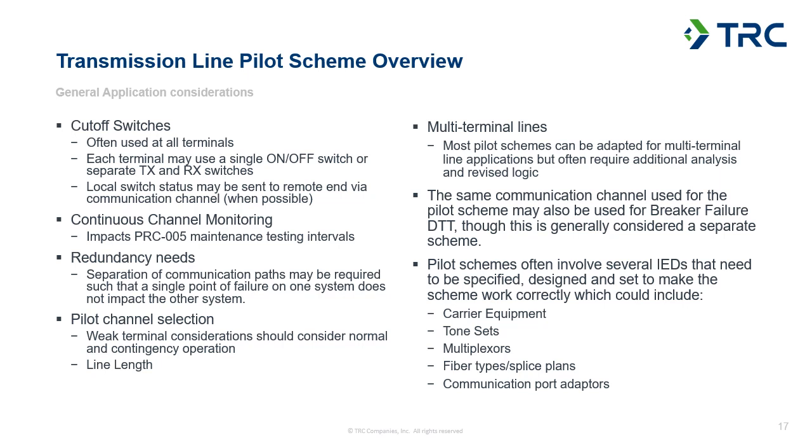And then lastly, the pilot schemes often involve several IEDs, and those would be your relays and communications equipment. They all need to be specified, designed, and configured consistently between all the terminals to make it work correctly. And that can include carrier equipment, tone sets, multiplexers, direct fiber optics.